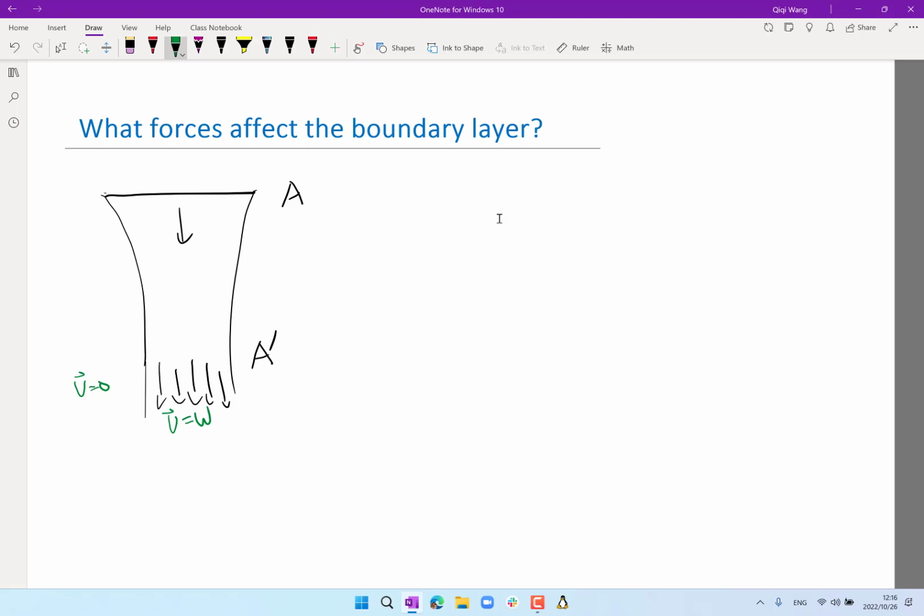Okay, when you cross the rotor disc, the velocity cannot change because of conservation of mass. Right? If the velocity changes suddenly across the rotor disc, if you draw a thin control volume around the rotor disc, then you would violate conservation of mass. So velocity wouldn't change. And the pressure actually changes suddenly. Right? The rotor pushing down actually increases the pressure. So basically there is a pressure jump without velocity jump.